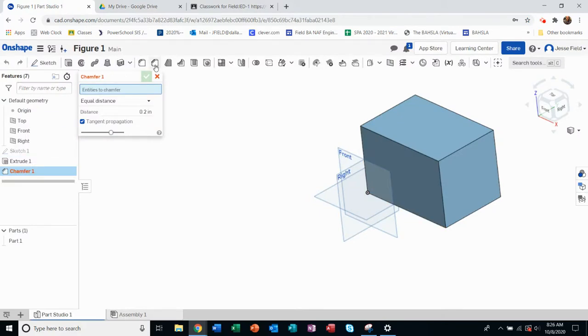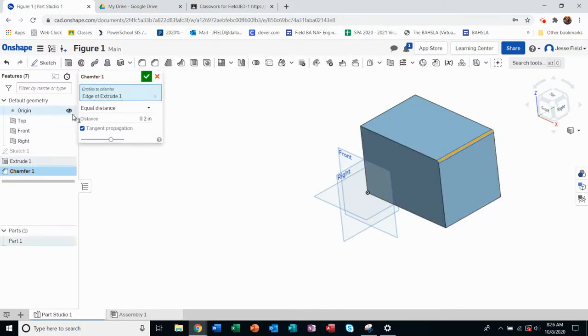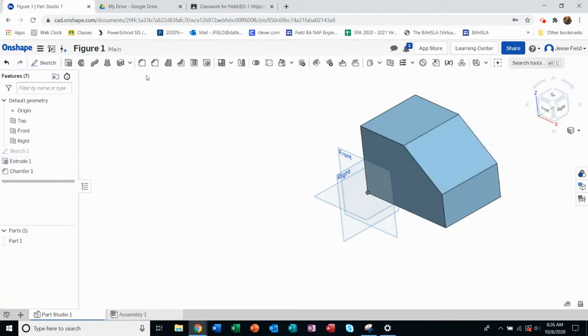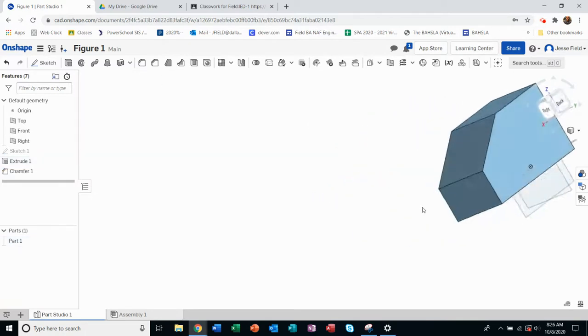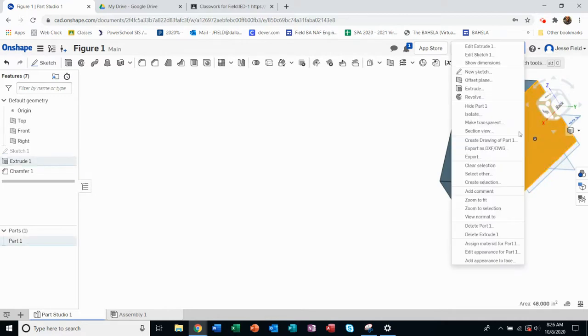So when you go to chamfer, and you can chamfer this edge, it'll actually let you do it by 2 distances. And I'm going to just go ahead and type this one in. So I'm not sure if that's the X direction. I can change them. Nope, that one was the Y. So I'm going to go ahead and make that one the 3, and that one the 4. See what that looks like. Yeah, that was right.